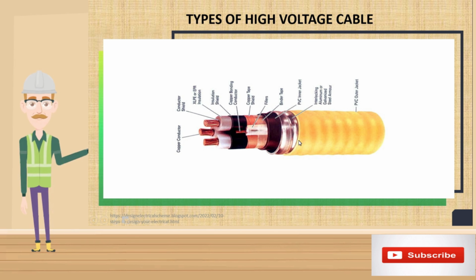The shielding of the cable is done in order to eliminate the corona discharge, leakage current and capacitive current, thereby reducing the possibility of insulation failure, electric stress and electric shock. The major differences in the type of cable used are, first one is the conductor type and second one is the insulation used to protect the cable.